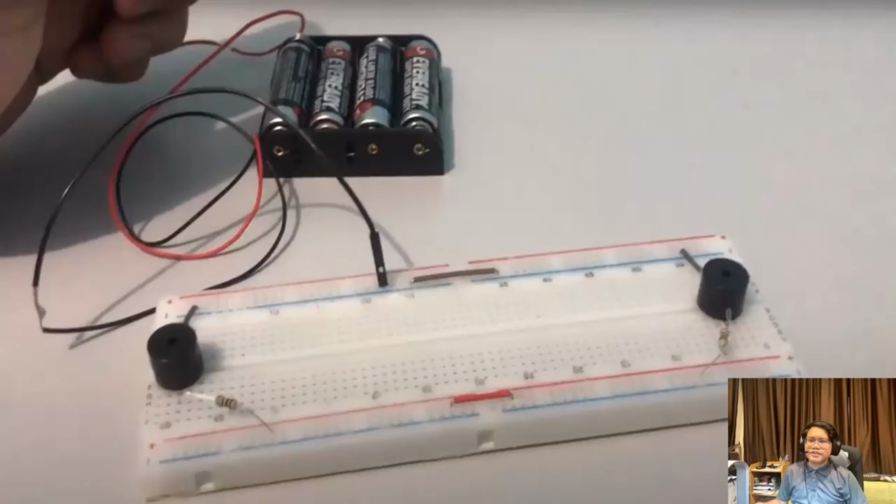The frequency of the buzzer can be varied by applying different resistance in the circuit. In our project, we use a 2000 ohm resistor for the buzzer to produce a 650 Hz sound wave and a 440 ohm resistor for the buzzer to produce an 850 Hz sound wave.